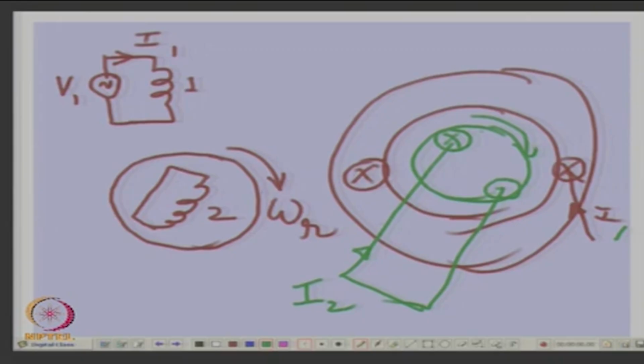Okay. Let us see what happens. The stator carries a sinusoidal current due to sinusoidal voltage, and let us see what type of fields it will produce. Producing sinusoidal current means this winding has a pulsating field again, is not it? So, it will produce a field which rotates, one plus omega and another minus omega, is not it.